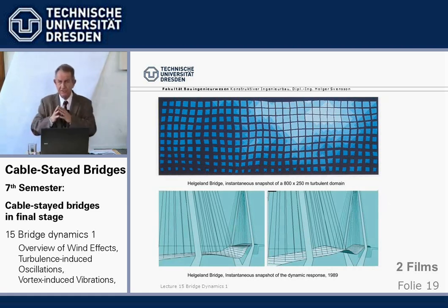Now, there is today a more sophisticated method, which Kovacs, for example, has developed. And that uses an analytical method. On one hand, the wind field with the gust characteristics as defined is created in the computer. That's this one here. And then we let this wind blow onto the bridge, for which we have a bridge model in the computer with the proper frequencies and so on.